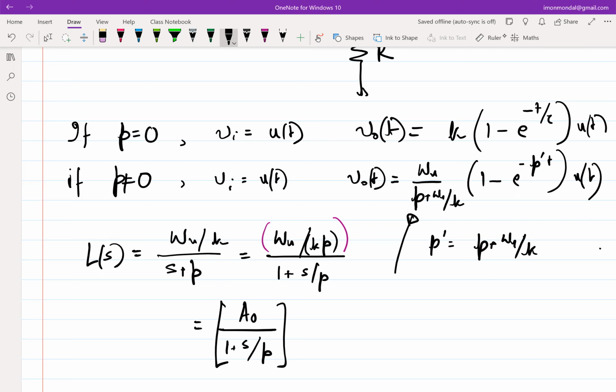So without again going into the proof of it, I leave the proof to you, do it yourself. Without going into the proof of it, what will be the approximate closed loop transfer function? How will it look on a Bode plot if I have a real integrator? So this is my L real of S. Now what will my H real of S look like? Use the same intuitive logic. How will it look?